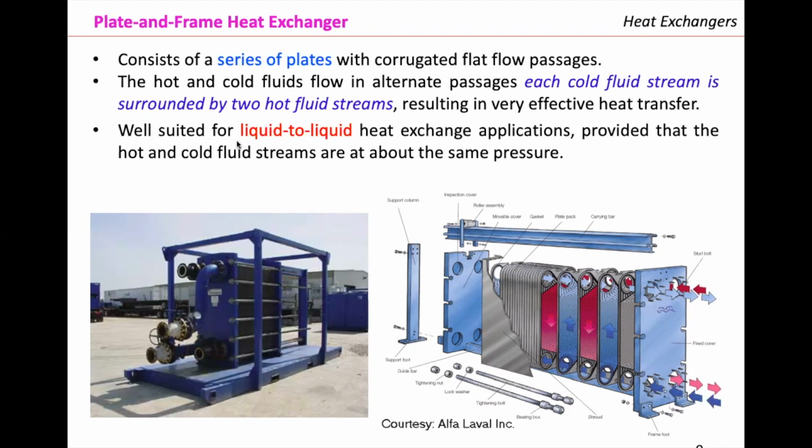So it is well suited to liquid heat exchange applications. That's important. This type of heat exchanger, we use typically for liquid to liquid heat exchange applications, provided that the hot and cold fluid streams are at about the same pressure. So this is good for liquid to liquid applications.